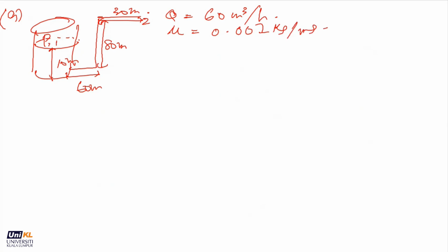First, we need the Bernoulli equation. Second, because we include a piping system, we need to calculate roughness, head loss. Before head loss, first you need to calculate Reynolds number to determine either laminar or turbulent flow.